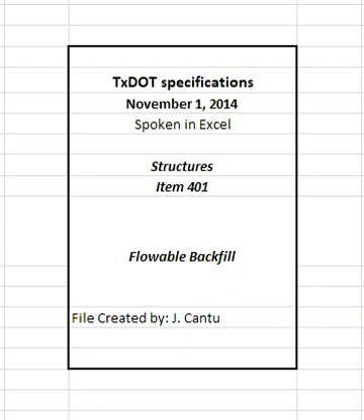3. Construction. Submit a construction method and plan, including mix design, for approval. Provide a means of filling the entire void area, and be able to demonstrate this has been accomplished. Prevent the movement of any inserted structure from its designated location. Remove and replace or correct the problem if voids are found in the fill or any of the requirements are not met as shown on the plans without additional cost to the department.